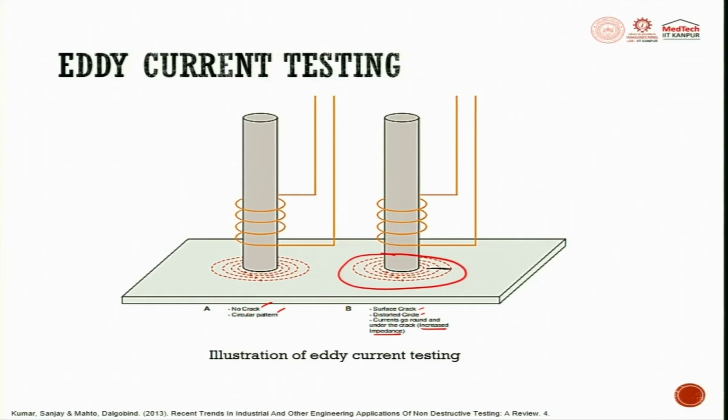The encircling coils here are to be used to test tubular or bar shaped products majorly. The product can travel in between, going up and down, with the encircling coil around it. Eddy currents could also be induced within the product itself. So it depends upon the kind of testing and the shape of the product that we have.